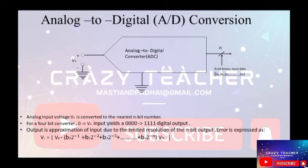When you give the maximum value Vx as input, you get 1111 as the digital output. So that is the design principle of this analog to digital converter. We'll see later in our course how to design these ADCs and DACs in different ways. But ultimately this is the thing that we want. If we give a 0 voltage, it should give 0000. If we give Vx, the maximum possible voltage, then it should give all 1s.